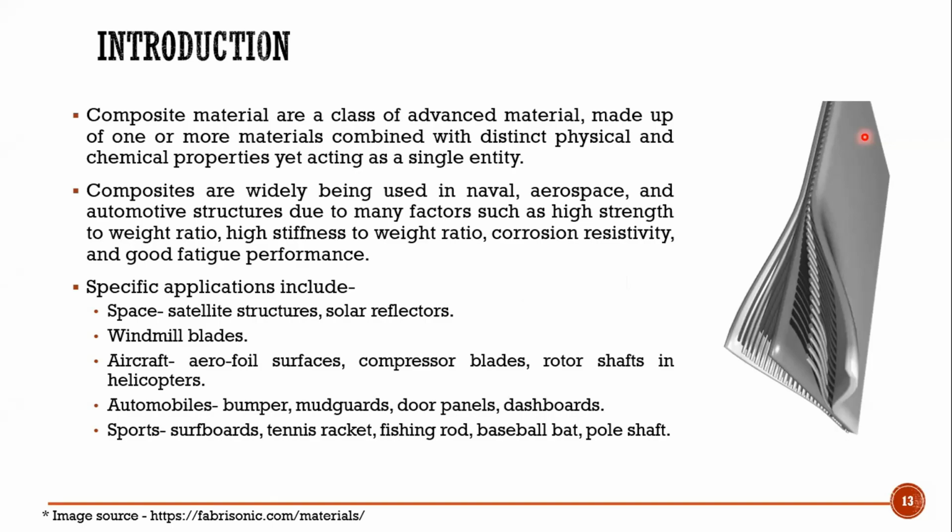They are being used in different applications like aerospace, automotive, and naval applications because they have a high strength to weight ratio and a high stiffness to weight ratio. Apart from that, they provide better corrosion resistance and fatigue resistance. Applications include satellite structures, aerofoil surfaces, mud guards, door panels, and in sports, tennis rackets and fishing rods, etc.